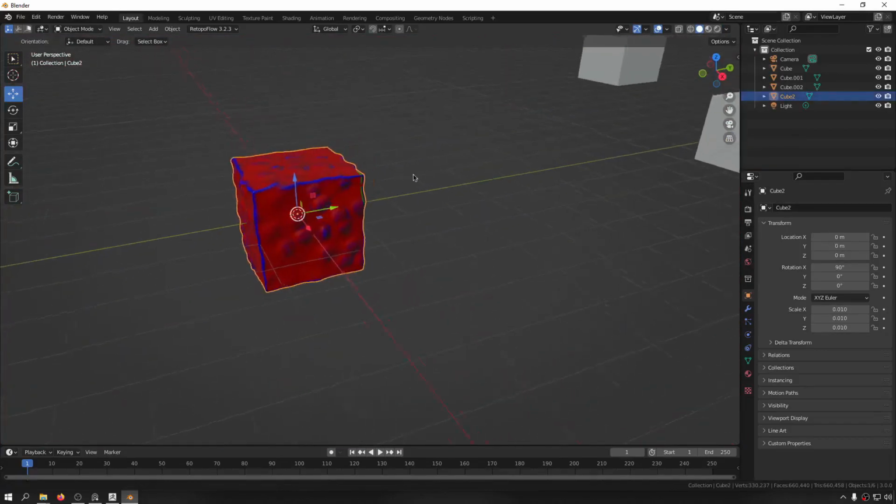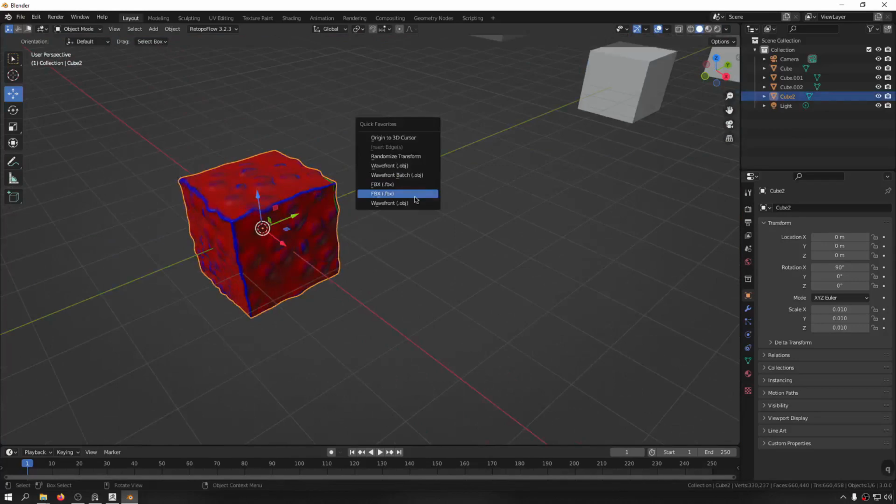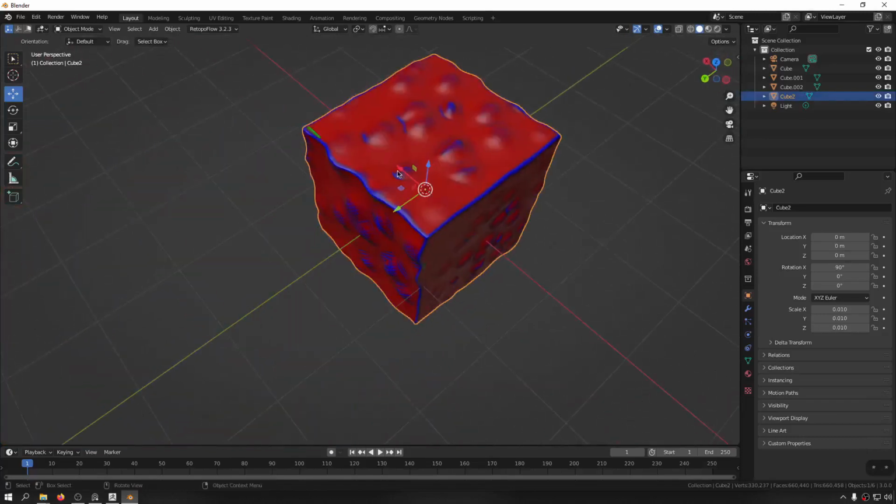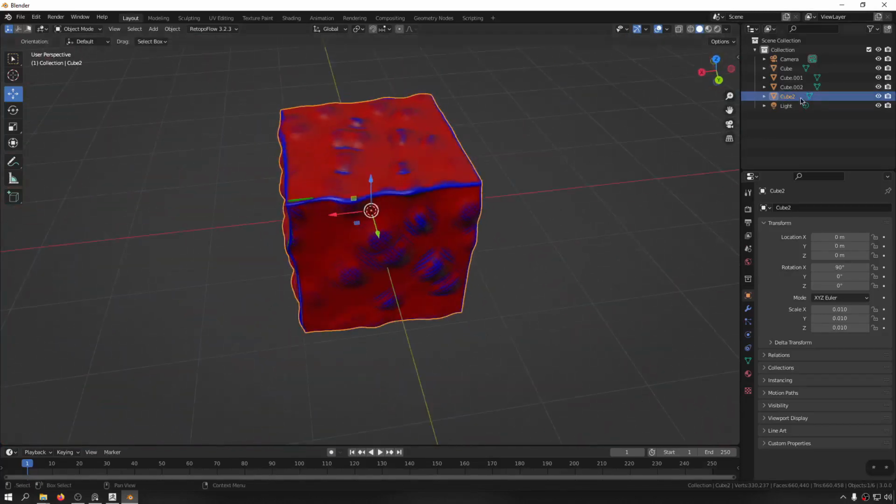So let's take this and export it. And I always prefer to bring the mesh into Blender and then export it from Blender so that I can change the names. For example, let's name it to a static mesh. Always when I'm creating meshes, I'm going to call them a static mesh, SM underscore nanite underscore test.